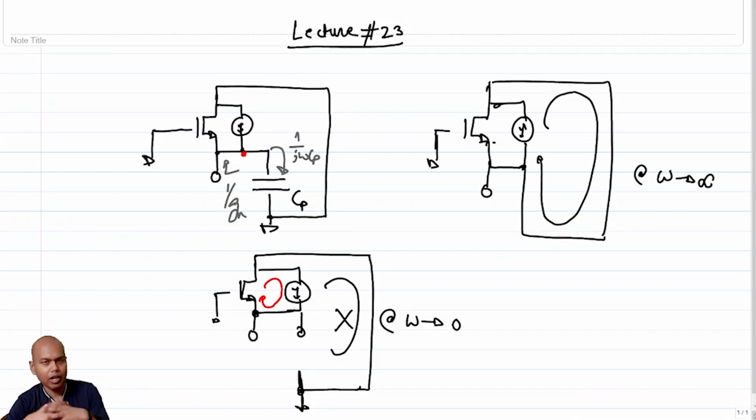You can probably be okay with even being 20x below, so below omega t. So that's why the design trade-off comes in. You do that rough analysis, and then you simulate and verify whether you really need to give that amount of headroom to be so far away from omega t, or maybe 1 decade away from omega t, or maybe 20x away from omega t is good enough, right? So that's the design call one has to make after 1 or 2 iterations of the design, right?